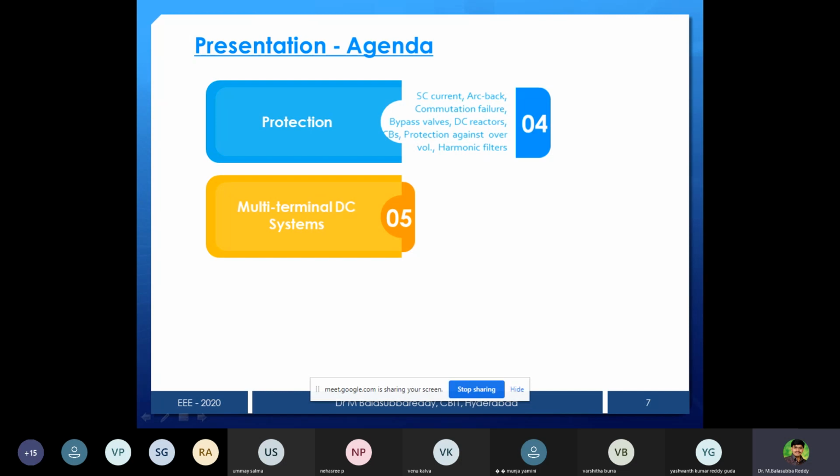the AC side, because once the AC side is disturbed, then automatically the controller output is also going to be disturbed. If the input is constant, then according to your firing angle you will get an average output voltage. But sometimes the input itself is fluctuating, and accordingly you have to adjust the controller in such a way that your output is maintained constant. Or if you want to vary it, you can vary it. Because if the input drops down, obviously the output is going to drop down, but we have to maintain it constant, so the controller has to take care of that.